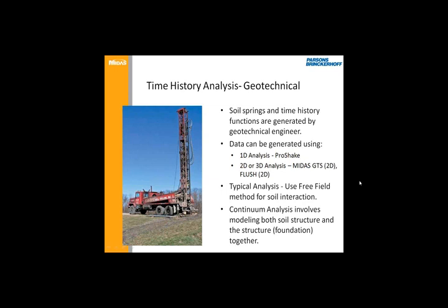So basically, soil springs and time history functions are generated by a geotechnical engineer. Depending on the size of your firm, it might be you. I work for larger firms, so generally we get our information from the geotech department. And the data can be generated either using 1D, 2D, or 3D analysis. So common software for 1D analysis is ProShake, and then you can use Midas GTS or Flush for 2D analysis.